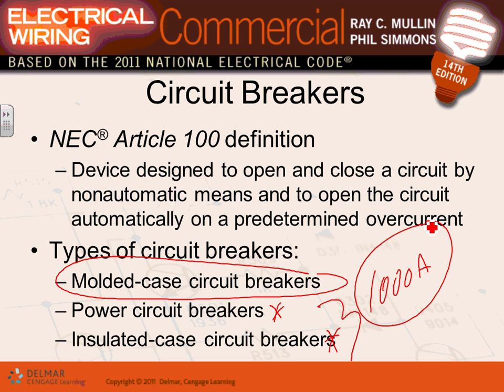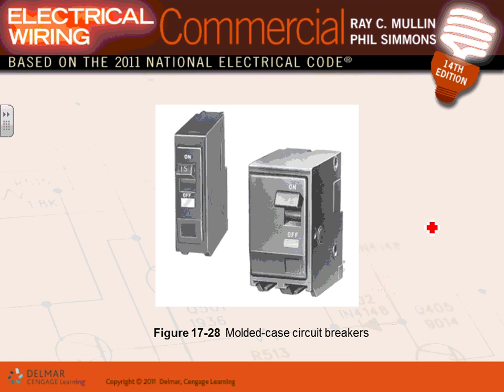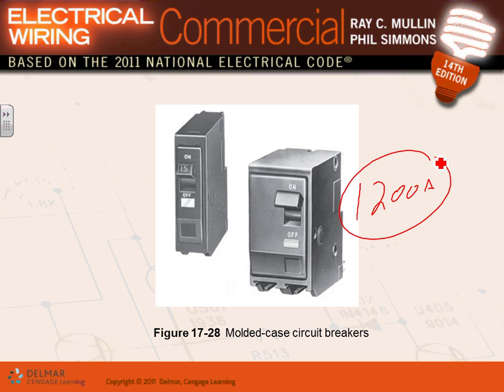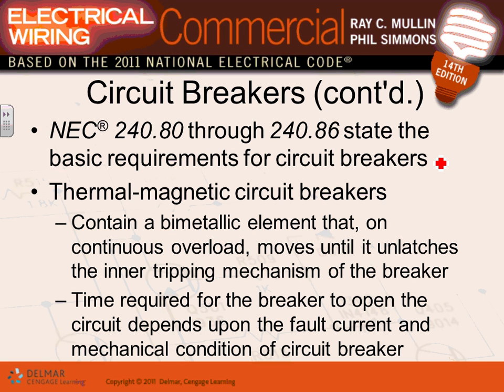Karen, these power circuit breakers are like a foot by a foot by a foot. They are really big devices, and they have a lot of gadgets on them. Here's your molded case circuit breaker. I believe they can make them up to 1,200 amps, if I remember right. After that, you can make the power circuit breakers and so on. Single phase, 3-phase, or 2-phase.